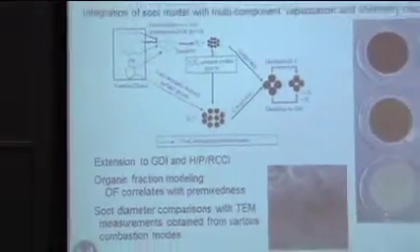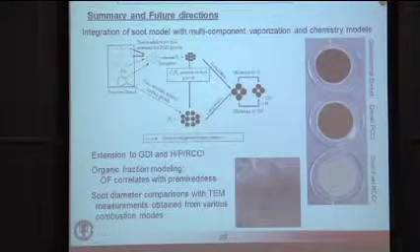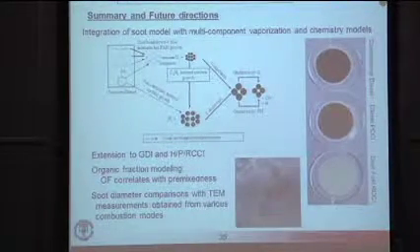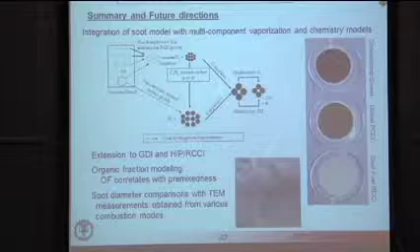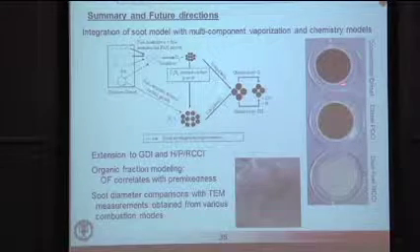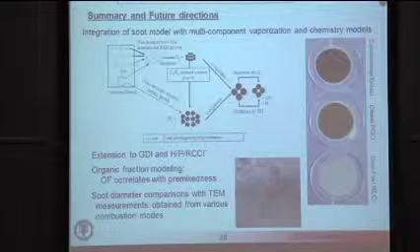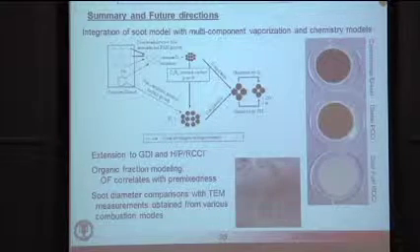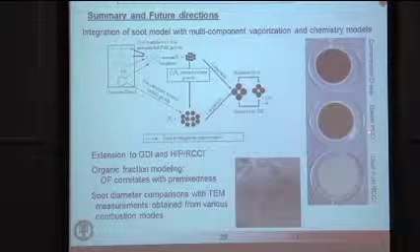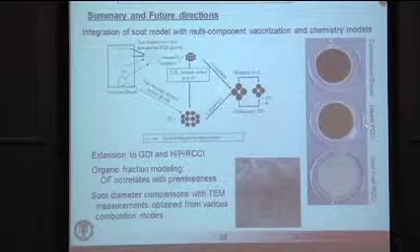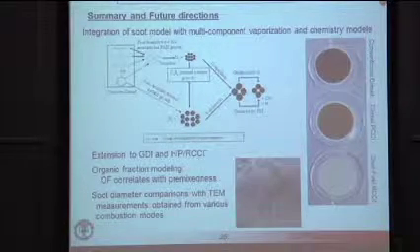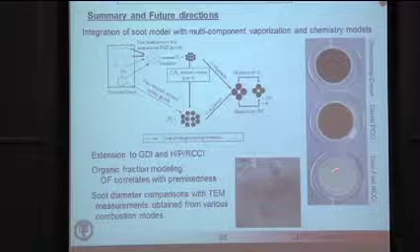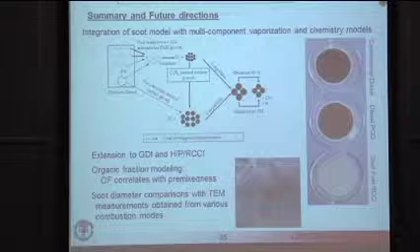The other thing that we've noticed recently, and tomorrow, on Friday, I'll be talking about some of the combustion work that we're doing currently with low temperature combustion, is that when you collect the soot on a filter, you see completely different looking soot depending on the combustion regime. For conventional diesel combustion, you get this black stuff that you see coming out of the exhaust of a truck in front of you on the highway. When you go to PCCI, this is early injection, premixed charge compression ignition, it turns kind of brown. And when you use dual fuel reactivity controlled compression ignition, RCCI, which I'm going to tell you about more tomorrow, you get what essentially just turns the paper a tan color.